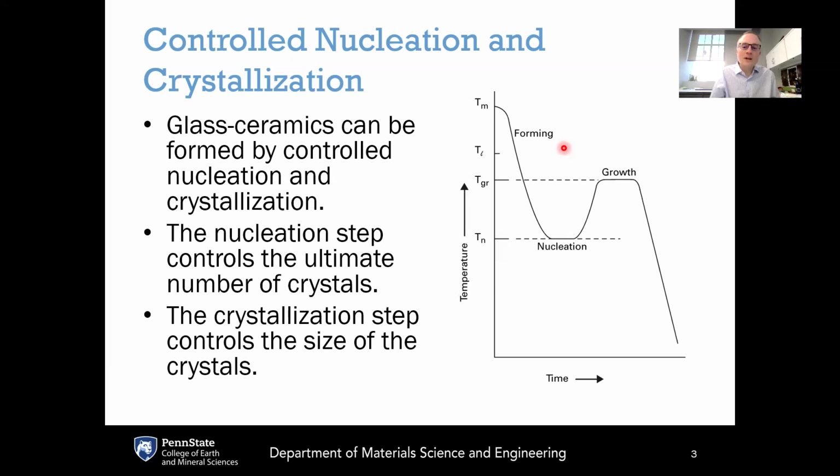With a glass ceramic, one of the key advantages is that the shaping and the processing of this material is done in the liquid state, not in a powder state or a solid state. And what this means is that we can run our glass factory through exactly the same steps that we would undergo for making glass products, for making glass ceramics as well. So we can shape, say, a glass bottle or a glass sheet or whatever shape we want. This can be molded or formed in the liquid state using liquid state processing. So in that case, there is no porosity. And in fact, in most glass ceramics, the amount of porosity is zero because of this liquid state processing. Then we take the glass that is formed. So whatever forming that takes place is done in the liquid state. It gives us this glass article.